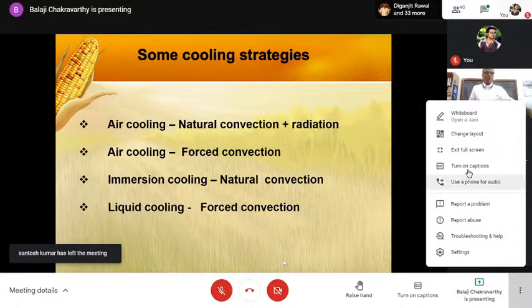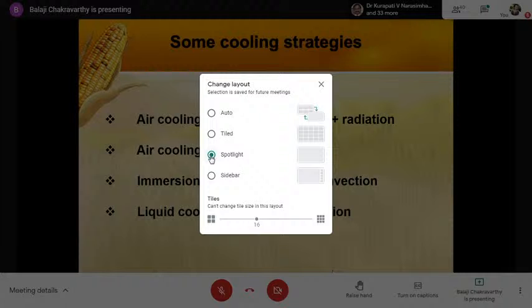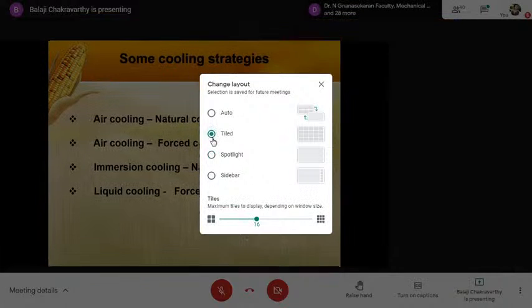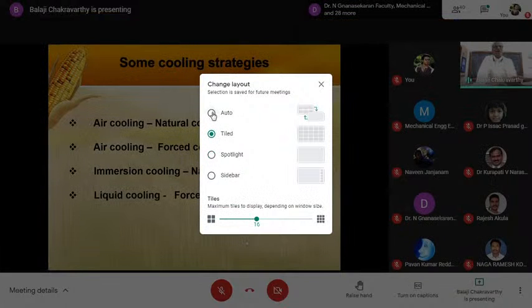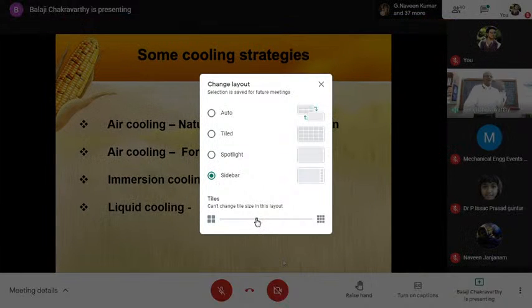But the idea is, once you do that, normally if it will take 30 minutes, now in 10 or 15 minutes, you touch it, it comes to about 38, 40, 42 degrees. That is the ideal temperature, around 40 degrees. The temperature will be such that it will be cold if you take it as coffee, right? The temperature of coffee is around 45, 48, so it should be lower than that. So that is immersion cooling, natural convection.